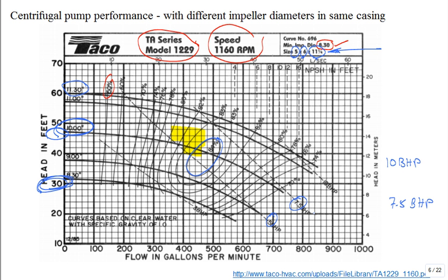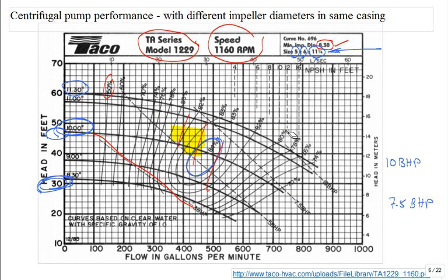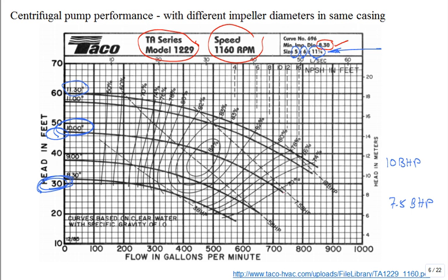So if you buy this pump and you anticipate staying below this line, you only need to put a 7.5 brake horsepower motor on it. If you buy this pump and you anticipate always staying basically everywhere below it, it's a 10 horsepower. So if you buy that pump, don't put a 3 horsepower on it and then try and operate out in that vicinity. The motor will have major problems. And what will happen? The motor will try to do what it's asked to do. It'll try to maintain that speed. The amperage will go up and you'll burn out your windings. So it won't last long. So that's one other piece of information that incorporates the efficiency, this 70%, 74%.